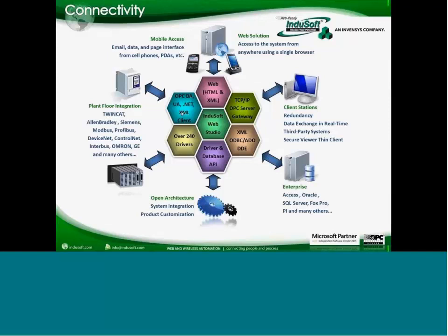Also, as part of the package, you have over 240 proprietary communication drivers. That means that you don't necessarily need an OPC server to use InduSoft to talk to your device, to talk to your PLC. We have drivers for the most known brands out there. We have one for TwinCAT that we're going to demonstrate today, but we have also for Allen Bradley, Siemens, Modbus, Omron, GE, and even the maybe less known PLCs, we may have a driver for those as well.